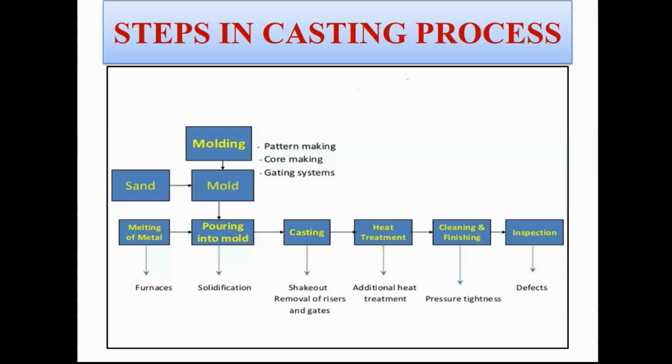First of all, this shot peening imparts compressive residual stresses on the surface, and you all know that the surface is the primary location for any failure to initiate. So there the compressive stress will nullify the residual stresses, and then it will also reduce the chances of any catastrophic failure arising from fatigue or any impact.